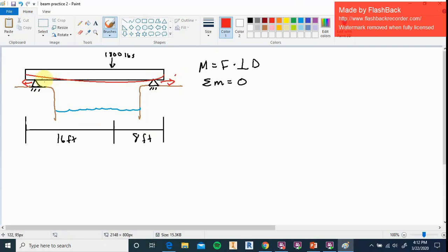So now all of a sudden, inside the beam, you have these forces that are pulling on each other, and basically what will happen over time is we get a crack here, we get a crack here, and the beam will start to pull itself apart because of these internal stresses created by the bending. So we have to be able to allow the beam to move.